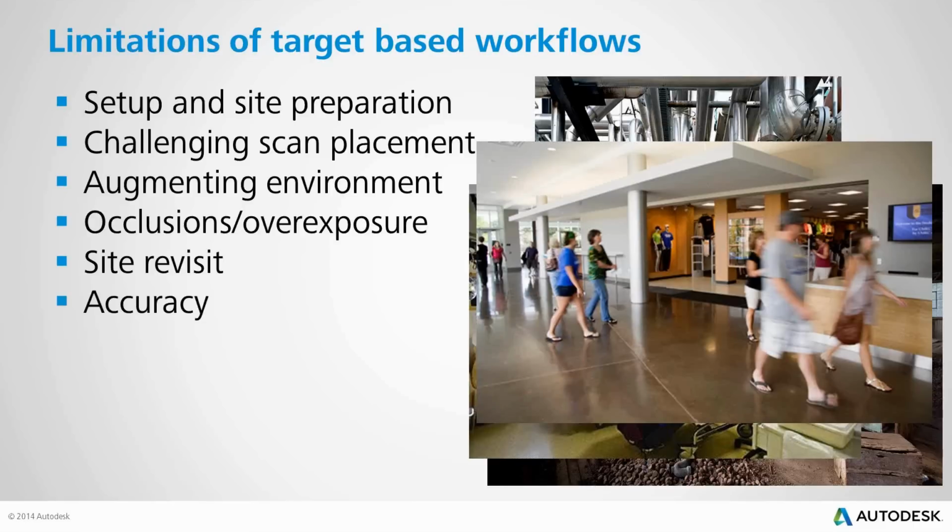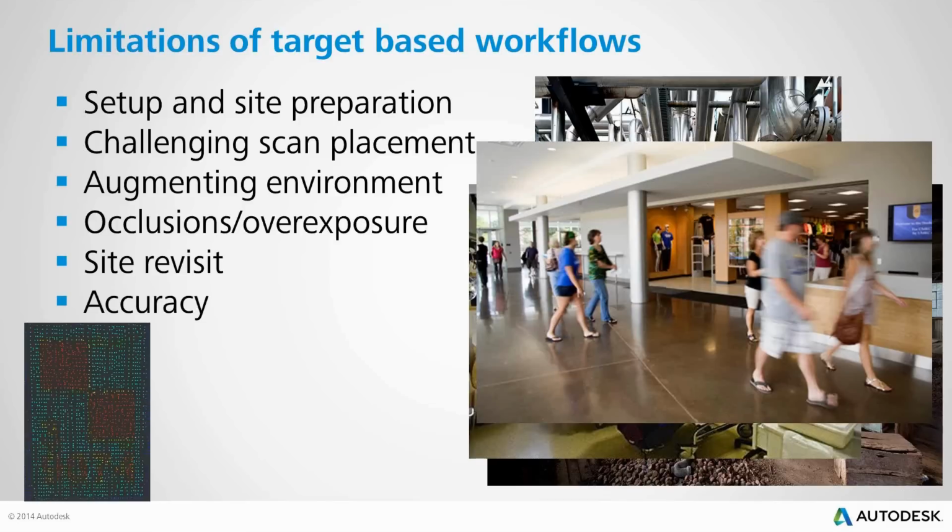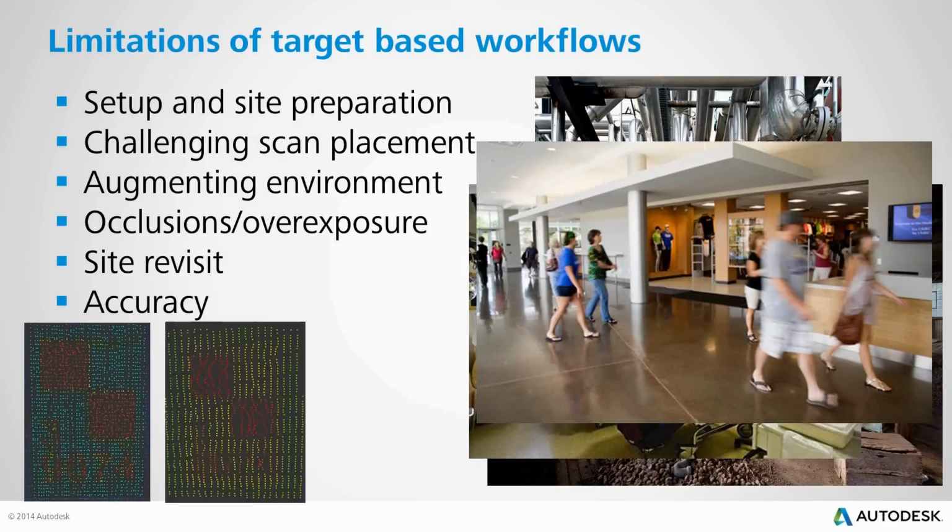Accuracy is an issue that's not often brought up with target-based workflows, but if you really think about what we're asking software to do, to extract the location of these targets, here's what a target actually looks like in a high-resolution scan at 3 meters. Each of these points has a little bit of noise, a couple of millimeters depending on the scanner and hardware quality. But we're asking software to find precisely where the center of this target is.